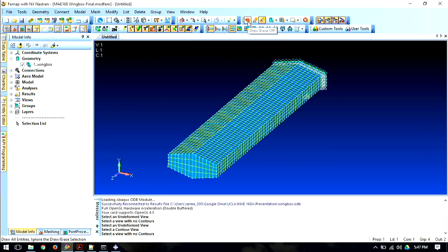Christian, can you tell me when they give you the model, it's probably a solid model? Usually designers will give you a solid model. So if you're really good buddies with them, you can ask them, hey, can you give me mid-plane surfaces of, say, for example, the skin? Otherwise, you have to do it yourself. You have to be able to work your way around CAD, either in the CAD software and export the clean surfaces that you want, or you have to mess with it in FEMAP, Abaqus, or whatever other software. You're generally never going to create your own geometry within the preprocessor. It has the capability, although it's very limited. But it's advised to just do it outside and bring in the clean geometry, because cleaning up the geometry can take a while depending on how good or bad your designer is.